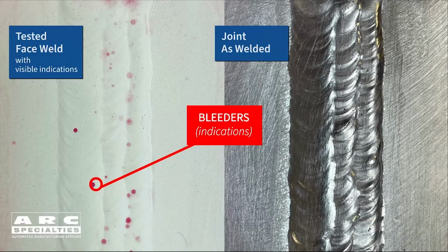After welding, these clad parts are inspected using liquid penetrant inspection. You spray a penetrant on the part and capillary attraction draws the penetrant into any surface defects. Then you spray a developer on top of that and the penetrant comes back out and is visible as red spots, which are called bleeders. Most inspectors incorrectly interpret these bleeders as porosity, but I've always thought they're probably oxide inclusions.